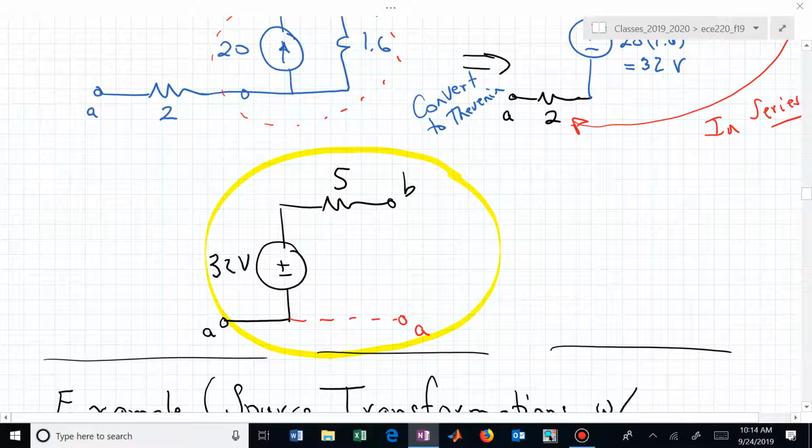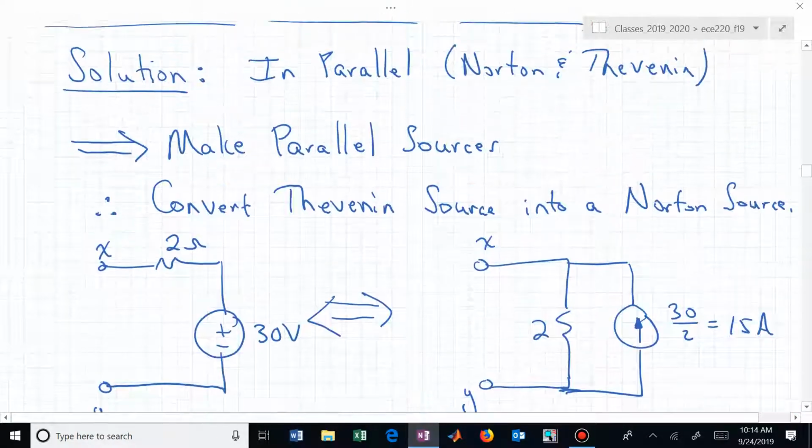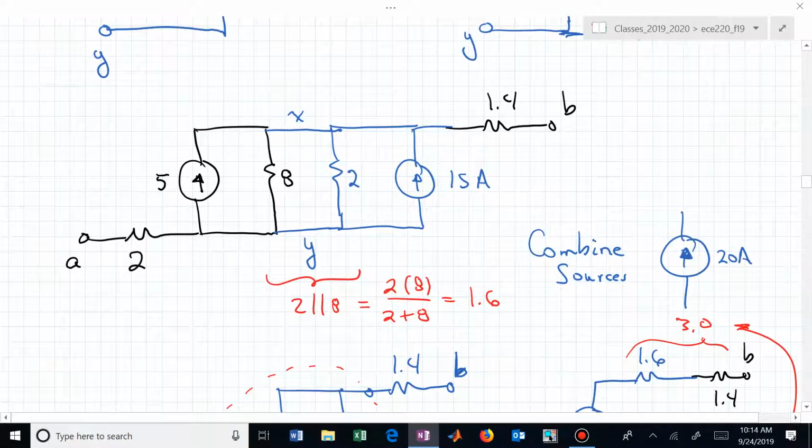I just need to know what's happening at the load between terminals A and B. So that now when I have 20 different resistors, I just have to analyze 20 simple circuits versus having to do the analysis 20 times with a current source and a voltage source, and they're all connected differently. You're avoiding that by doing this fun simplification.